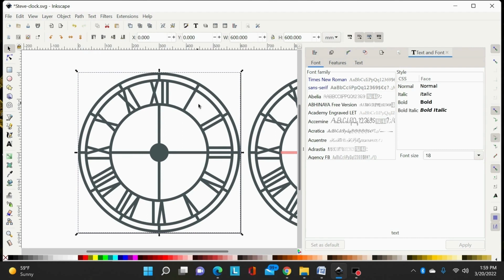So that's how you fix that. Just break apart that main design. While you're holding shift, click the outside contour to unselect it, union all the inner bits, then page them up and difference them from the main design there. And now that fixes the problem.